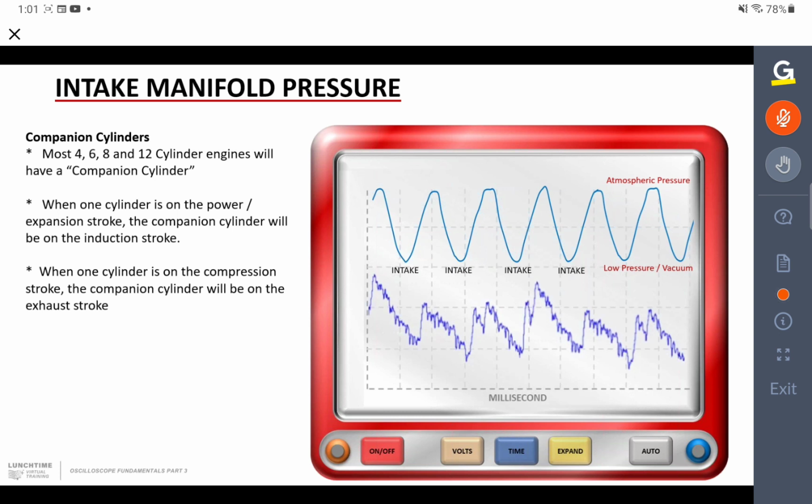Now, in reality, if you hook up a pressure transducer, the waveform might actually look more like that. You will see some really strange and lumpy waveforms, but you can still see that there is a lower peak there, lower peak there, lower peak there, although it's not a very low peak, that one. We'll come back to that in a minute.